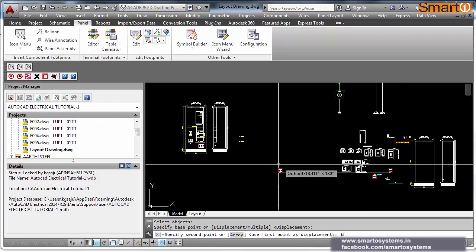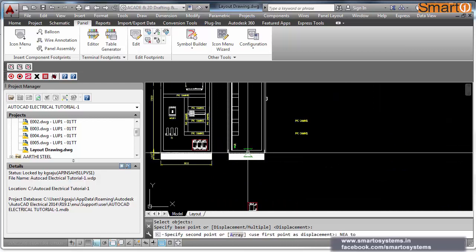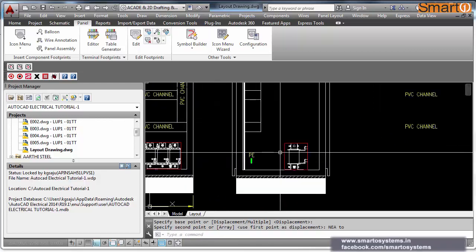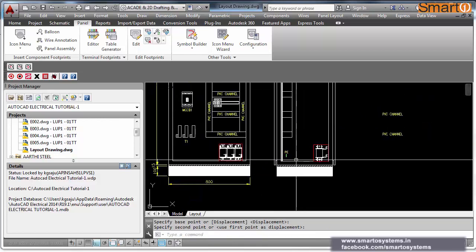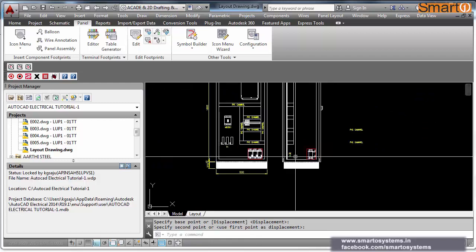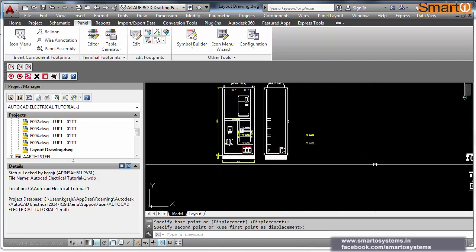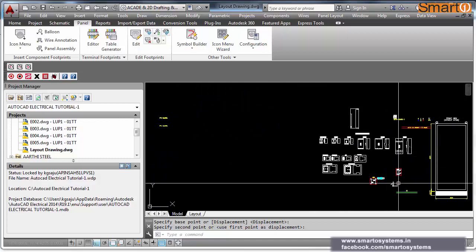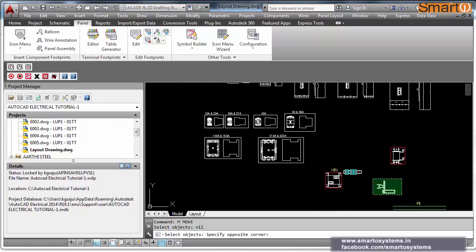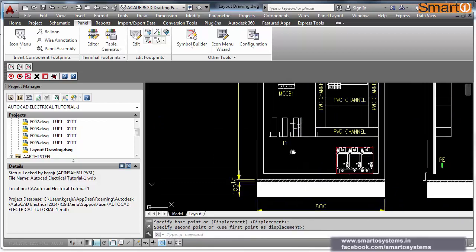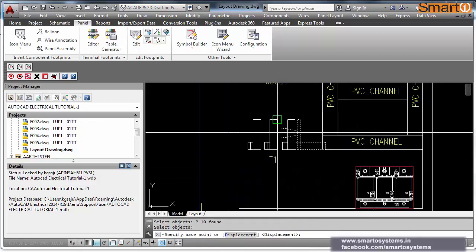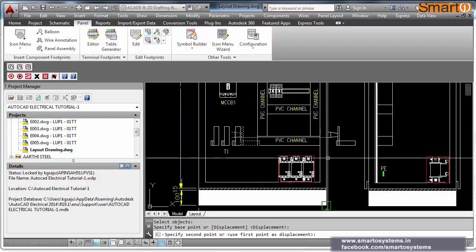This is overall. Now at the bottom I can see a choke. So I will bring a side view of a choke here. I will keep it here, somewhat on the front side, because my cable entry is through the bottom, so it won't restrict my gland plates for smooth cable entry. Now these bus bars, I have a block for that too.